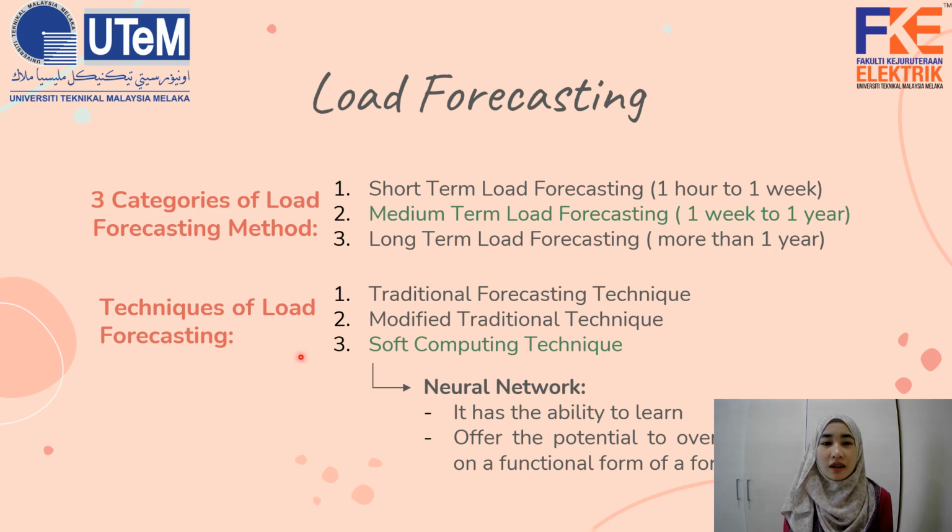Next, techniques of load forecasting. There are traditional forecasting technique, modified traditional technique, and soft computing technique. Soft computing technique is the most recent technique. It's more advanced than the other previous two. So neural network is under soft computing technique. We use neural network because it has the ability to learn and it offers the potential to overcome the reliance on a functional form of a model.